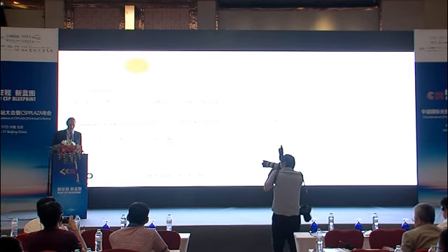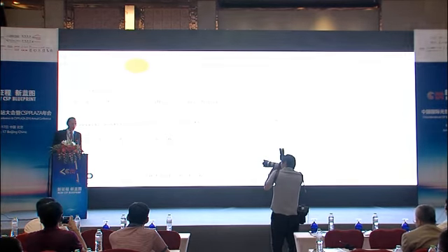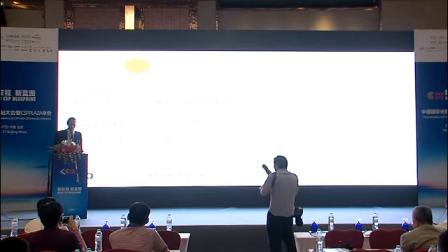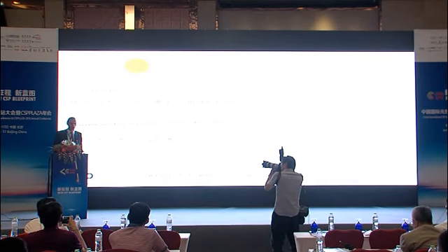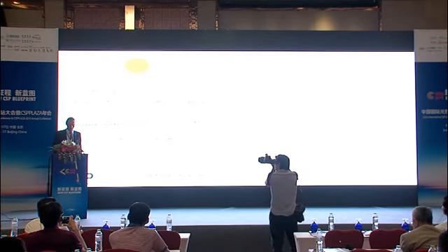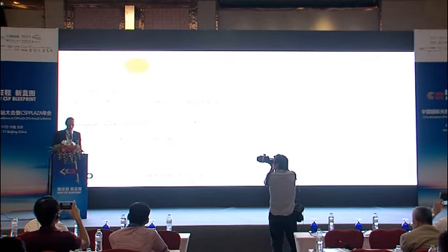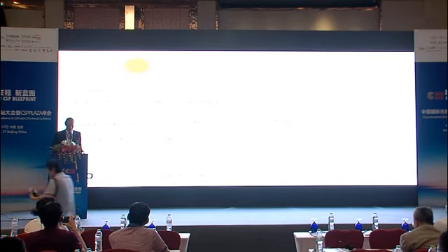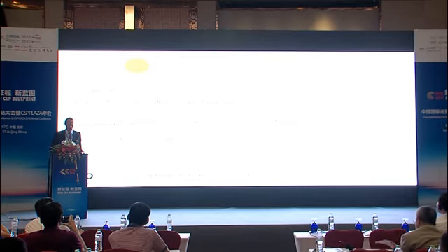So the steps in here are between 4 and 6 meters, and the collector is even broken up. It's not another continuous loop with a shared pylon. There's a step in between. So that means with a 1 degree inclination only, what the most collector suppliers can do, you end up with a technology like that. But the question was, can we not just incline the collector system to actually be in line with the natural ground levels?